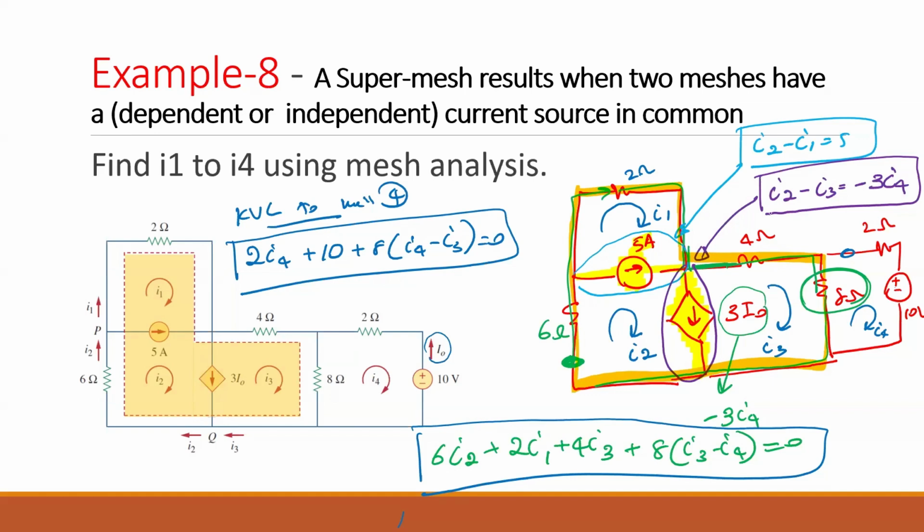So if you understood how to write the 4 equations here, KVL to 2 meshes, KVL to super mesh, and the KVL to mesh 4, you have to understand why we made all 3 into 1 mesh, because there are 2 shared current sources, and how to write the KVL to the super mesh, because these resistors are shared by different currents, so you need to properly write it.